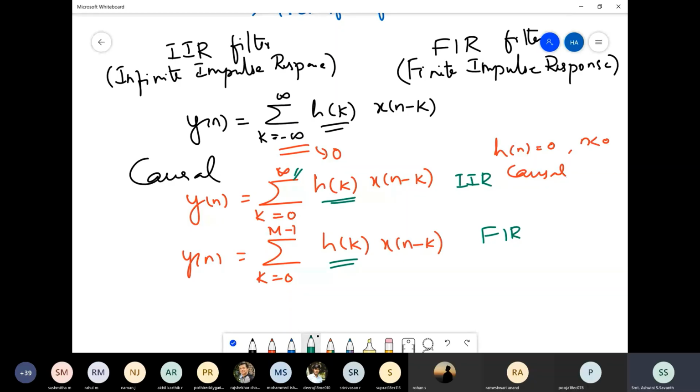So this is also the difference equation representation of a filter in general, right? Why difference equation? Because you are relating x of n and y of n here. You could also have terms y of n minus 1, y of n minus 2 and all that. We have written the difference equation before, right? The difference equation is one representation of a system where you're relating the input and the output. Is that clear? Now there are some more differences between an IIR and FIR filter.